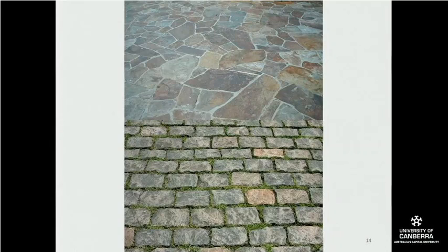What a substrate is, is the material that sits underneath your paving. If you were noticing that diagonal path with the compressed crushed granite sand topping beside the library, going from the library over to the well, the substrate there was really some sort of bluestone gravel, which was really hammered down before they put the granitic sand on top to hammer that down.